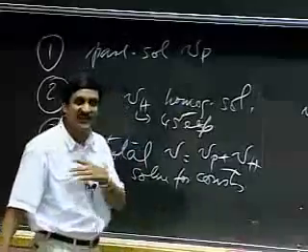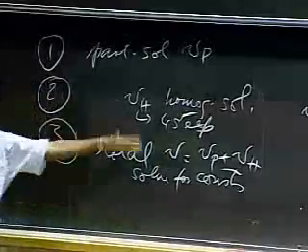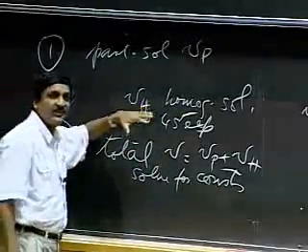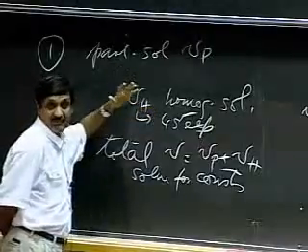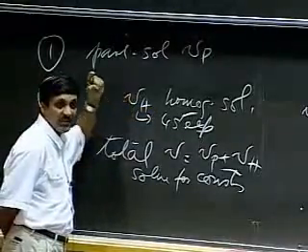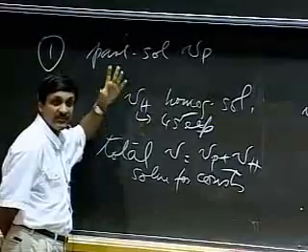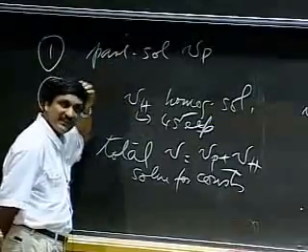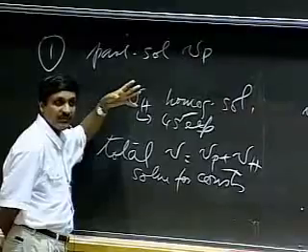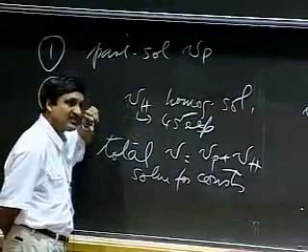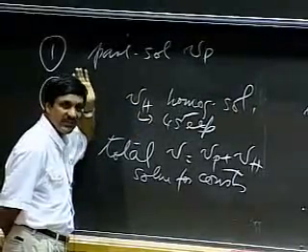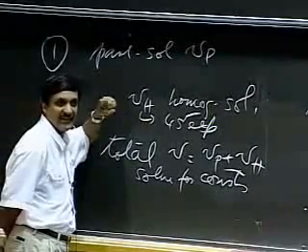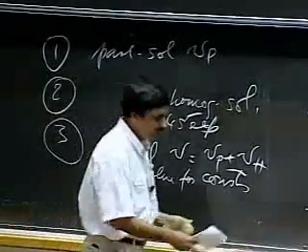You close your eyes and do exactly what you did for RCs, you'll get to where you want to be. So you assume a solution of the form A e to the st, substitute that into your homogeneous equation, obtain the characteristic equation, solve for the roots, and then write down your homogeneous solution. Same set of steps again and again and again until you get bored to tears.